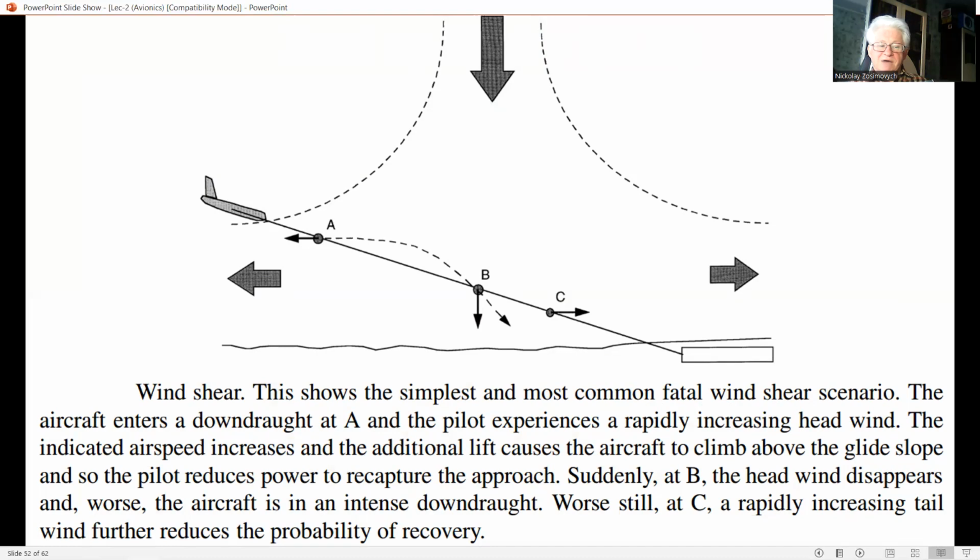In circumstances, however, during a terrain escape maneuver where the terrain is visible, the flight path vector, or FPV, displayed on the HUD provides an unambiguous presentation of whether or not the terrain will be missed. If the FPV is overlaid on terrain ahead, the aircraft will hit it, and in this situation the crew must decide on another course of action as opposed to holding on to see what happens.